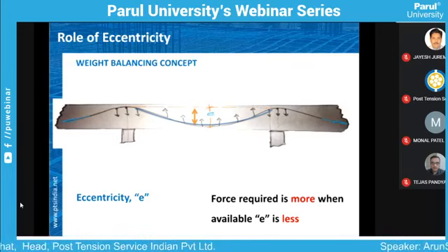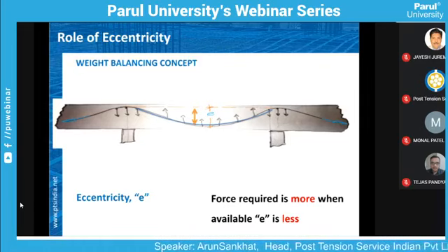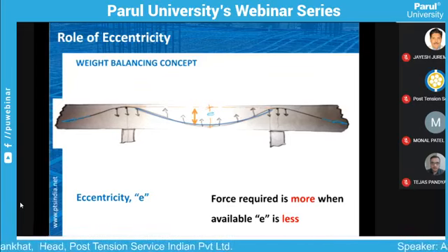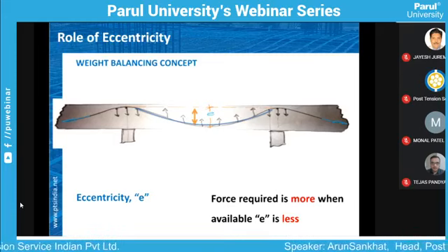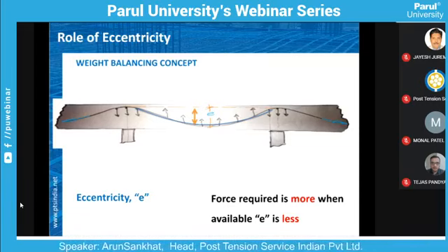but this would not be the actual case when you go in practice. The client always wants something extra, something more, something well value engineered. So as a part of value engineering, what the client most wants is to reduce the depth. To reduce the depth in an RC member is, you can say, difficult. So the easiest method is to introduce PT when there is a requirement of the depth needing to be minimized.